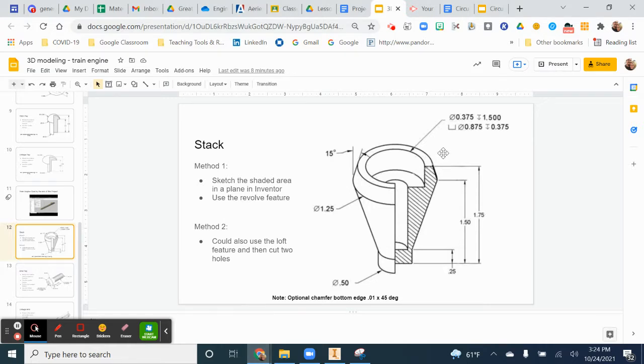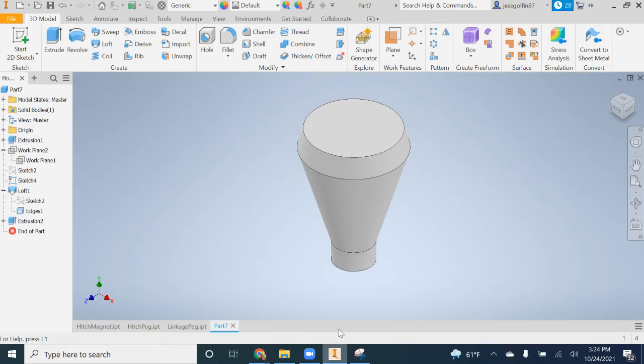But now the only thing missing is we need to create the holes in the stack where the smoke is going to come out. There's two cuts. We're going to use extrusion, but we're going to do the opposite, or cut the material out. First, I'm going to start a 2D sketch on this plane.